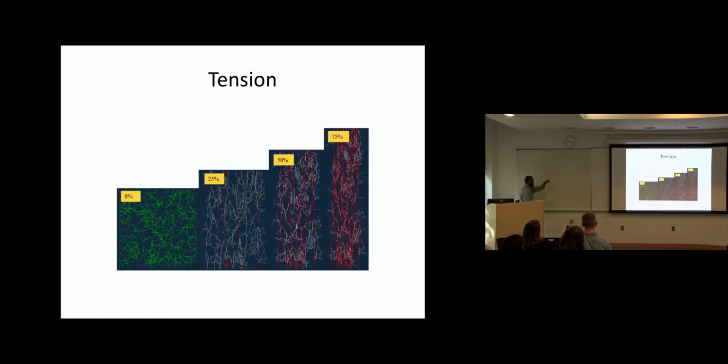If I apply tensile stresses, here you have a bunch of random fibers. When you pull it, you see all these fibers align. And further deformation really requires stretching of these fibers that were initially random but now are aligned. So the point is, if you take only linear elastic materials but cross-link them and align them, that can actually impart nonlinearity to the material, okay?